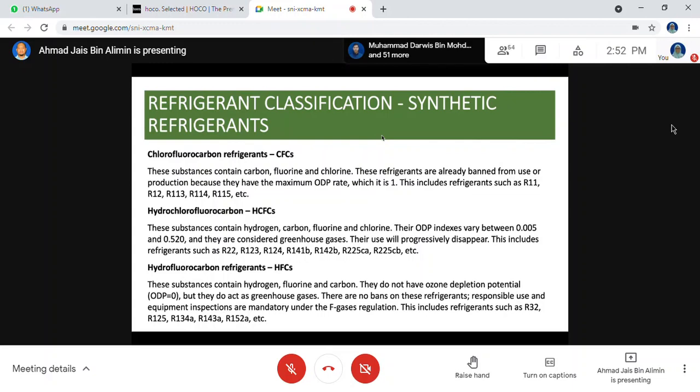Okay, but once you start to play around chemically with all these different elements and gases or refrigerants, then we term that as synthetic refrigerants. Okay, so bahan penyejuk buatan. Okay. CFC is one of the most famous examples, followed by the hydrochlorofluorocarbons, HCFCs, and then we also have the hydrofluorocarbon refrigerants.